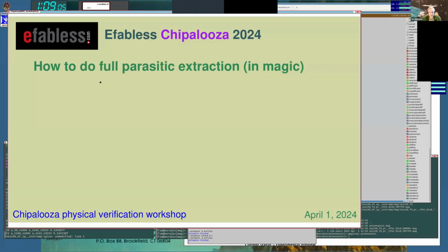Now, moving on, how to do full parasitic extraction, which is the one that you really need to do especially for a sensitive analog design. Do not use X to spice R thresh. If you look up the command reference for X to spice, you will see R thresh. It looks like it is equivalent to C thresh. It is a form of parasitic resistance, but it's something called lumped resistance, and it only shows up in .sim files, and it is not read or understood by any tool that I know of. It's an interesting concept, but it's not the one that you want here.